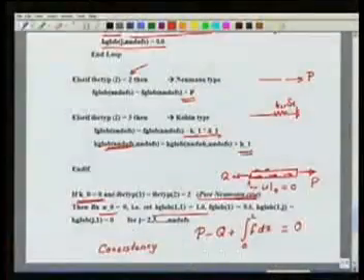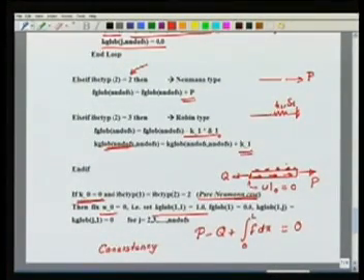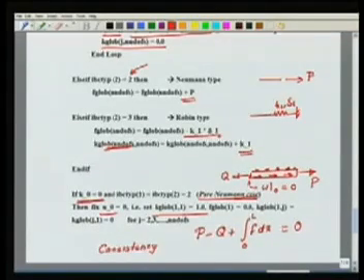If I have a distributed spring, say, somehow it is lying on an elastic support, then what happens? Automatically the rigid body mode is constrained against, because you cannot have a constant deflection for the bar in this case. Because if you have a constant deflection, then the spring is going to have a force, and that is going to counter the effect of the other forces. So in this case your stiffness matrix is not going to be singular. That one should check, that in case when k0 is not equal to 0, I have the same problem as I have done here. My stiffness matrix should not be singular. This is a check for your program.